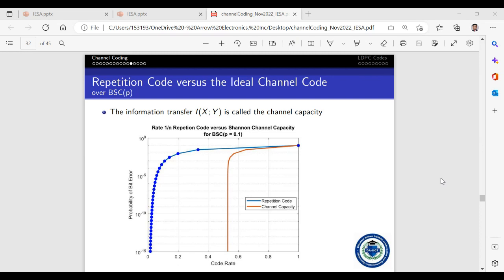If you're transferring images and videos, you would want to operate at 10 to the power minus 5 or 10 to the power minus 6. And remember the 99.99999% number that I gave for URLLC applications. There, the outage probability will be even lower than that. So outage probability depends on where the application will stop being functional.